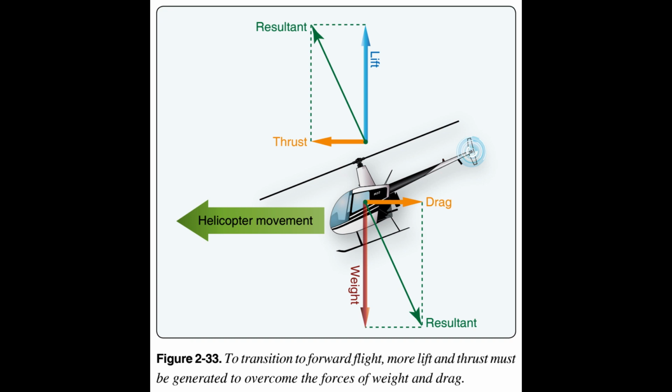Continued acceleration causes an even larger increase in airflow through the rotor disc, up to a maximum determined by drag and the engine's limit of power, and more efficient flight. In order to maintain unaccelerated flight, the pilot must understand that with any changes in power or in cyclic movement, the helicopter begins either to climb or to descend.